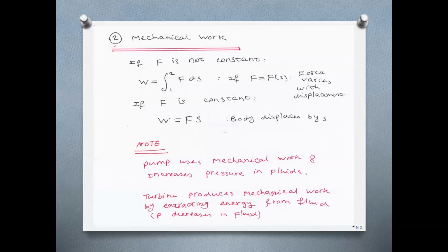The pump adds a fraction of that energy, depending on the efficiency of the pump, to the fluid, and the mechanical energy of the fluid increases. So at the outlet of the pump, the mechanical energy of the fluid is higher than at the inlet, because the pump increases the energy, the pressure, and by that the mechanical energy of the fluid.